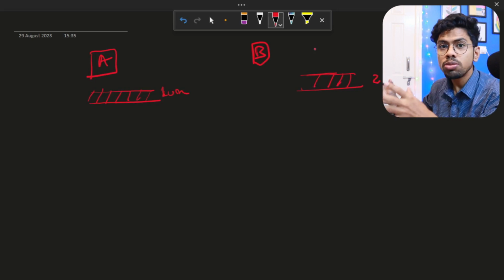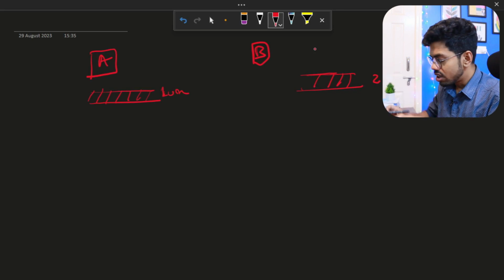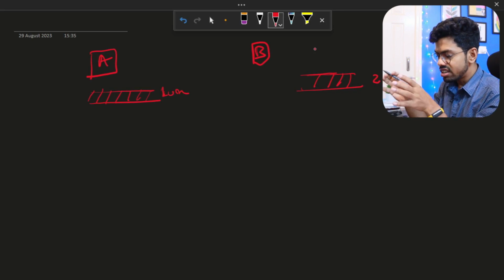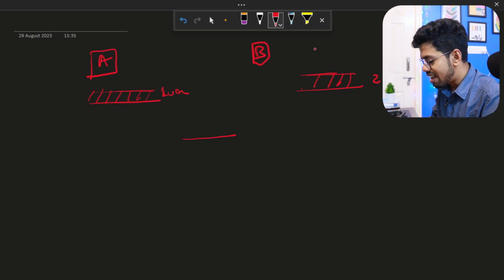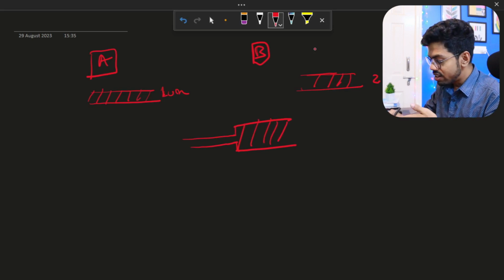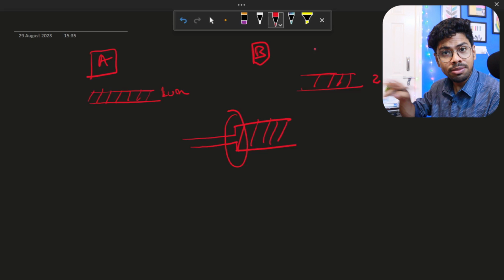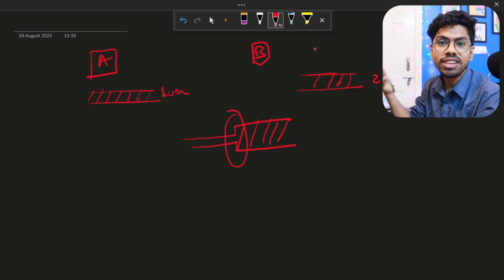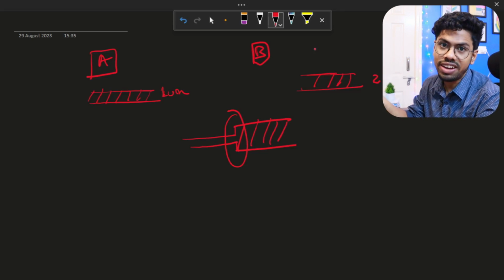But finally these two blocks will come inside one chip, right? So when I integrate these two, I'll get 1 micrometer M1 here and 2 micrometer M1 there. This kind of thing might be allowed but might result in DRC errors, right?